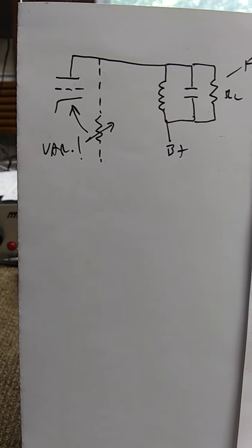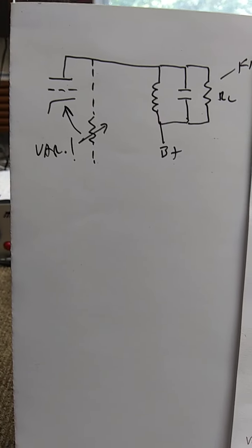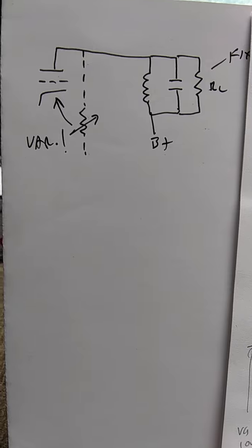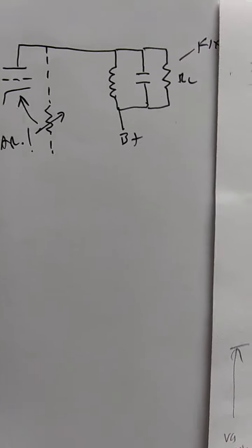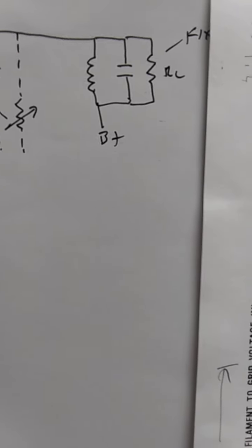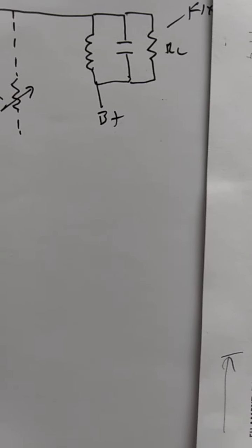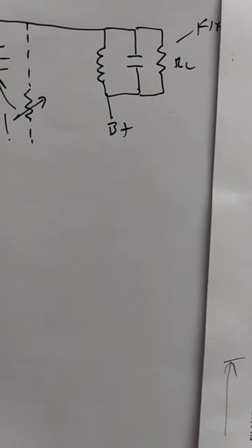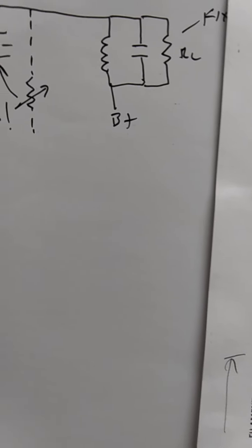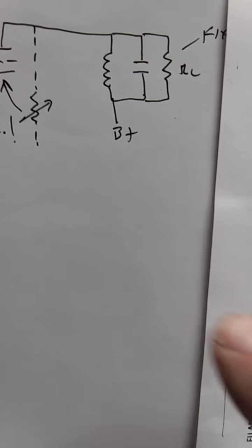So, it is not possible to have a resistor in the plate and put a pi network across the tube to the output. It will fail. Now, this type of circuit here with resistance is what's used in Drake TR3 and 4. The resistor, for example, for the final driver is actually in series between the B plus notation and the tune tag.